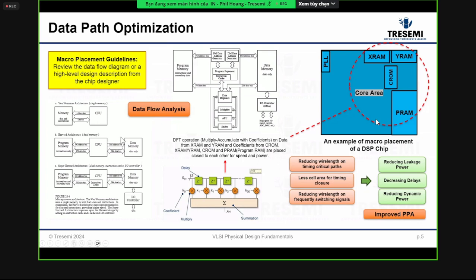You have a signal coming in, you sample it, you get a series of data that comes in and just keeps on shifting and being operated upon. It is a process that cleans up the signal, does some filtering, etc. So this happens continuously when you turn on the phone and you're hearing and communicating. So to do this right, and usually this is a speed path, meaning that because the operations require a computational unit, you want it to be very fast, and you want low power. A cell phone needs to save power.